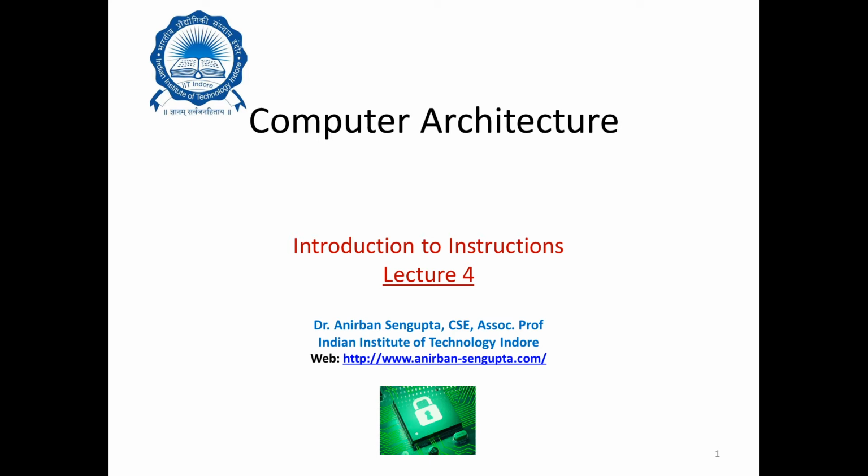Today what we are going to look at is an introduction to instructions, and by the word instructions we basically mean how the computer perceives instructions, converting them to a series of binary numbers that it can execute through hardware. So now we are ready to explain the difference between the way humans instruct computers and the way computers see instructions. Instructions are usually kept in the computer as a series of high and low electronic signals and may be represented as numbers. In fact, each piece of an instruction can be considered as an individual number, and placing these numbers side by side forms an instruction.